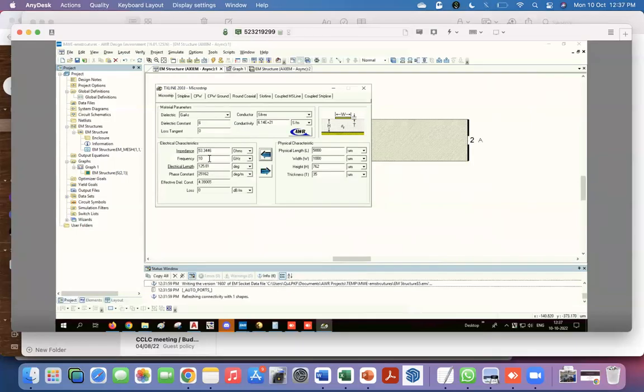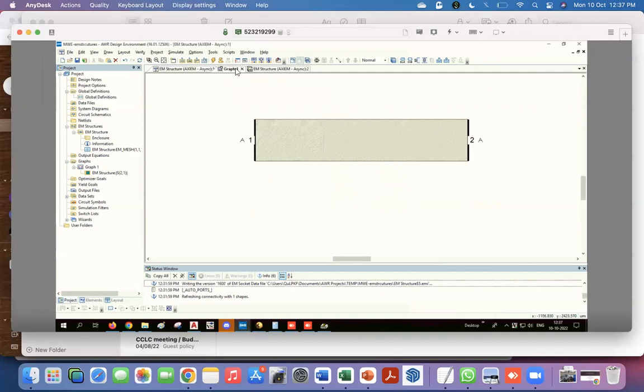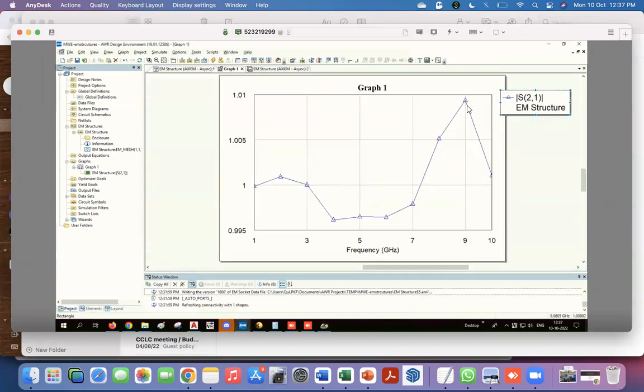So if you just have a nice 50 ohm transmission line with nice 50 ohm ports on either side, what do you expect in the transmission? Just one, right? Everything is transmitted, which is basically what you are seeing, but as Pania pointed out, at some point it is giving 1.1. This is actually one of the first pitfalls of finite element simulations. Even though you think the software should handle it, because this is an unphysical situation, this is a numerical calculation, right? So if things don't balance out exactly, you can get results like this. This is one of the things you have to be careful about.